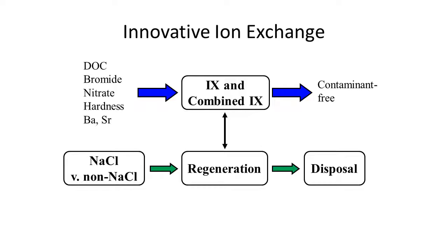But potassium chloride has some niches. Potassium is healthy for soil, whereas sodium is harmful for soil. So in terms of land application disposal, if you were to use potassium chloride, that could have more uses in land application than sodium chloride, because of how potassium interacts with soil. Whereas with sodium bicarbonate, we see some niches especially for disposal to wastewater plants, where the sodium bicarbonate would add alkalinity. If you're doing nitrification, you need some alkalinity, and sodium bicarbonate disposal could give you some. So that factors in here, but then again, it's got to work. Right, that's the other piece of it. It's got to work as well.